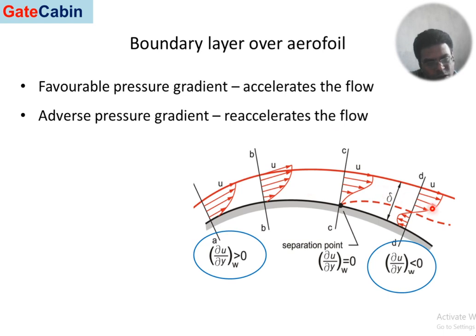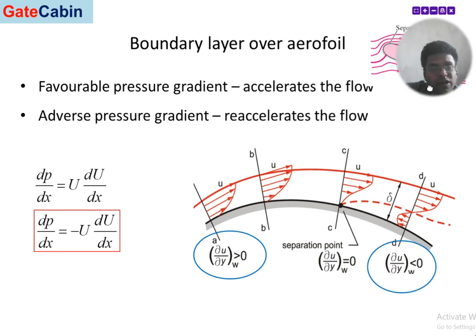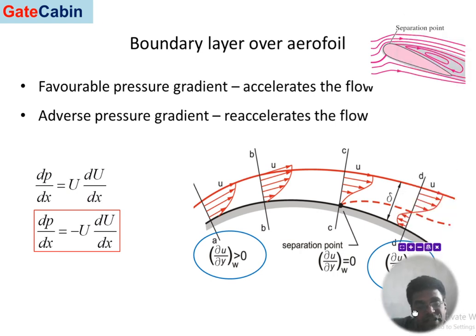In place of moving forward, like I told you, the external flow tries to interfere or interact with the low pressure air on the surface of a solid, right? The favorable and unfavorable pressure gradients can be represented by means of these derivatives, right? Then why is it important? The adverse pressure gradient and the deceleration of a flow results in flow separation, forming a separation bubble on the surface of the airfoil.